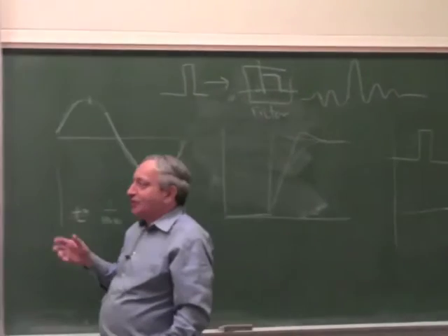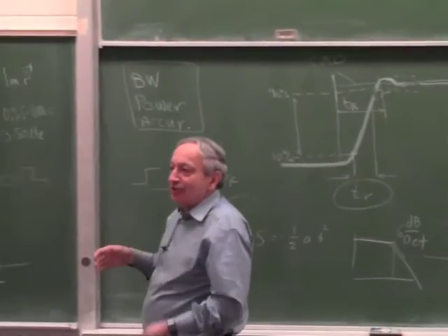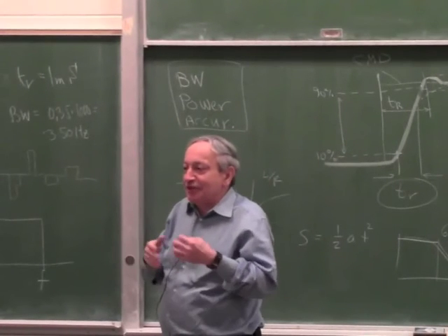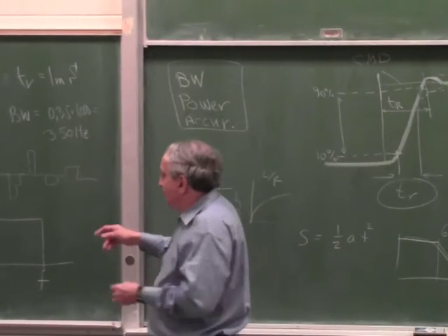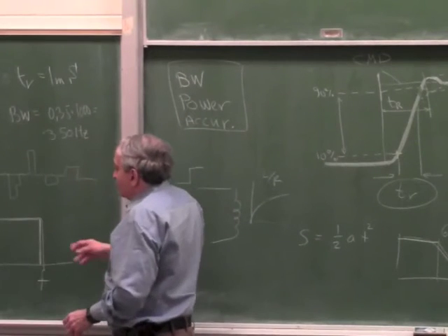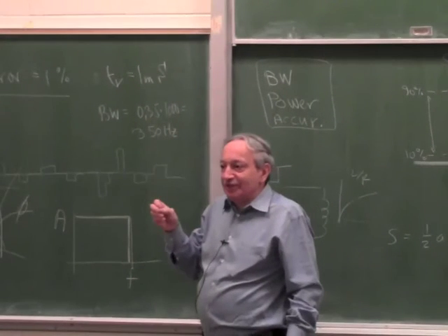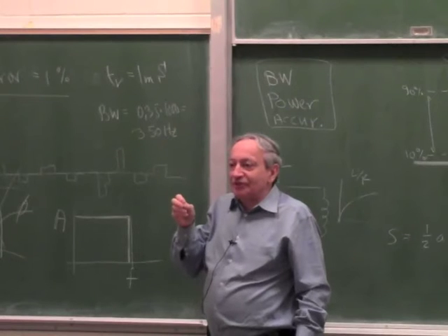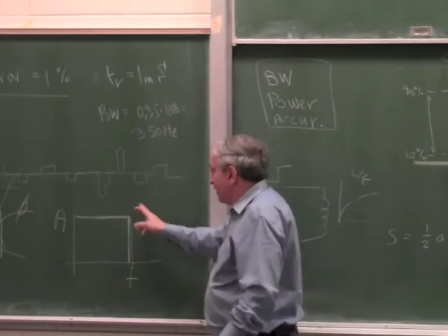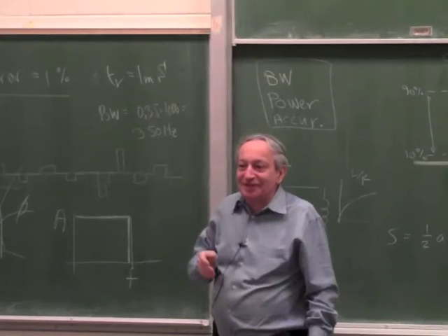So the filters which are very sharp, have perfect forms in the frequency domain, usually have much delay built in and much phase shift built in order to achieve this thing. And the reason you know that is the steeper the slope is, the more poles you have in the filter, because each pole gives you 6 dB per octave. So if you want 100 dB per octave, you need many, many poles, right? And many phase shifts, many delays.